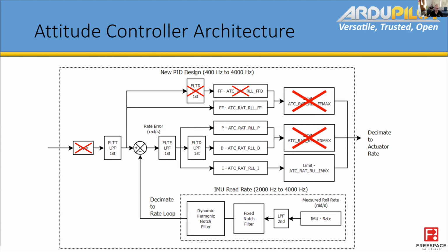So it's sort of a mix between the FFT-based source of that RPM and the throttle-based one. The other thing is that we need to window where we look for that primary harmonic, and using the throttle-based value to make sure we get that window right is another option.